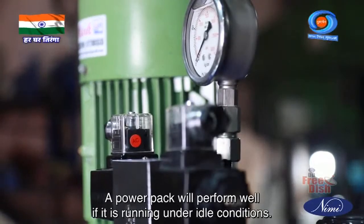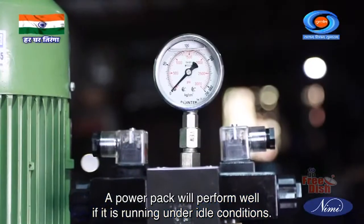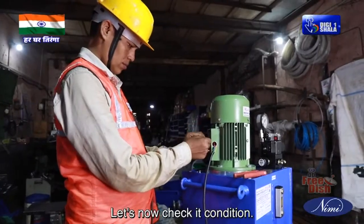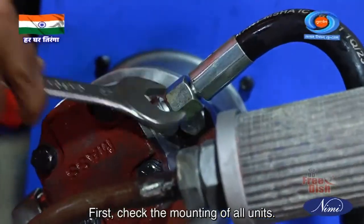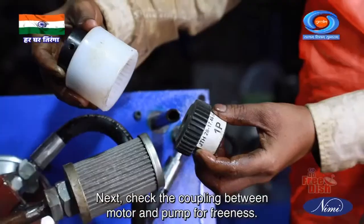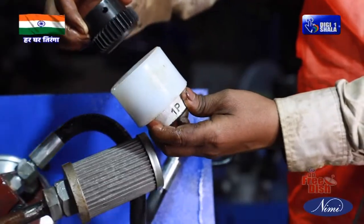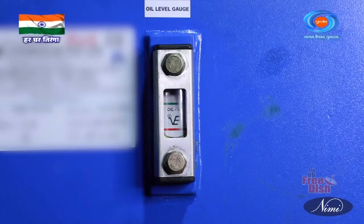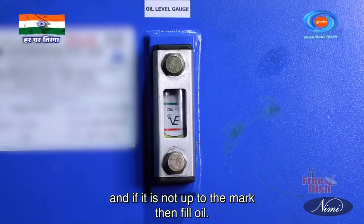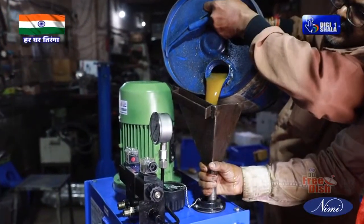A power pack will perform well if it is running under ideal conditions. Let's now check its condition. First, check the mounting of all units. Next, check the coupling between motor and pump for freeness. Check the level of oil in the reservoir, and if it is not up to the mark, then fill oil.